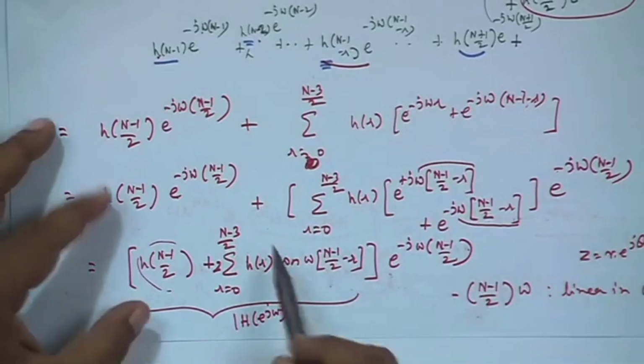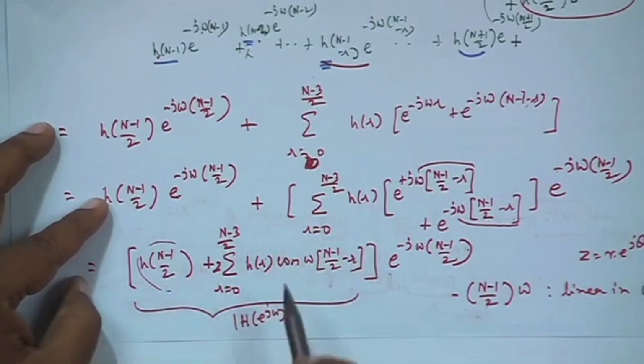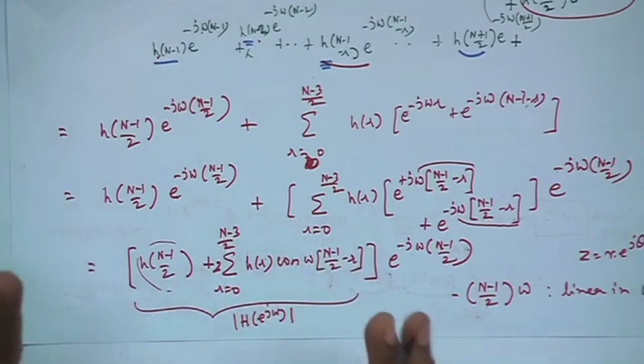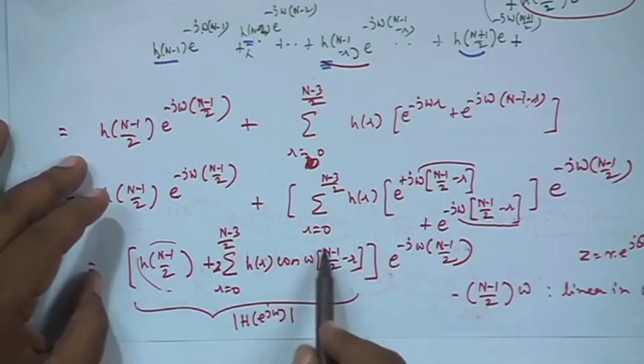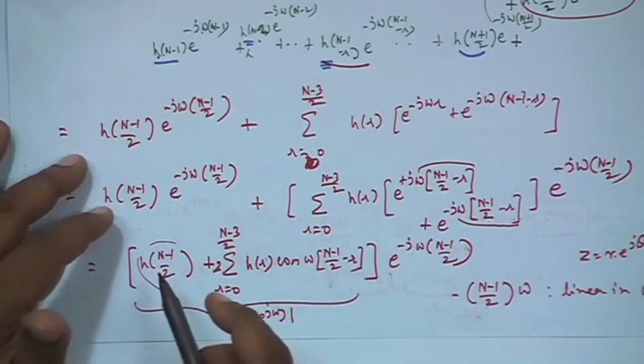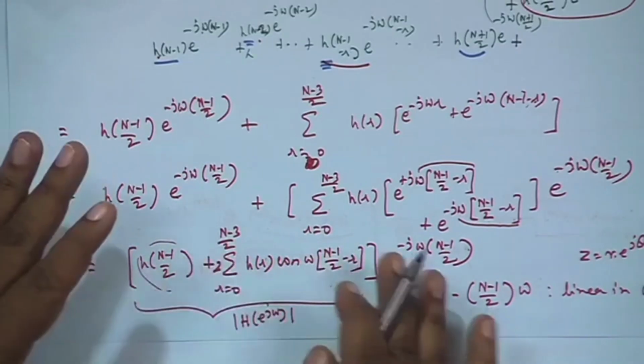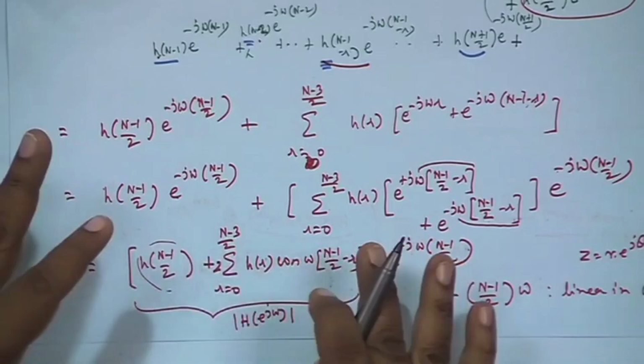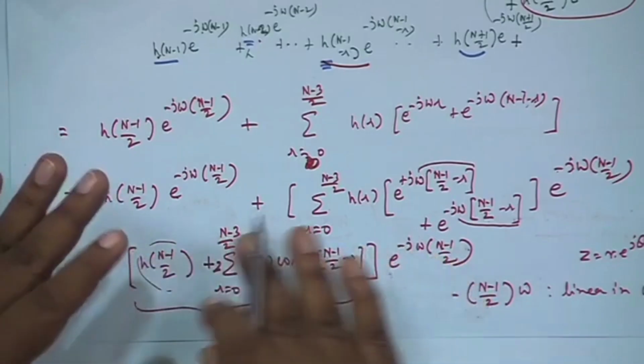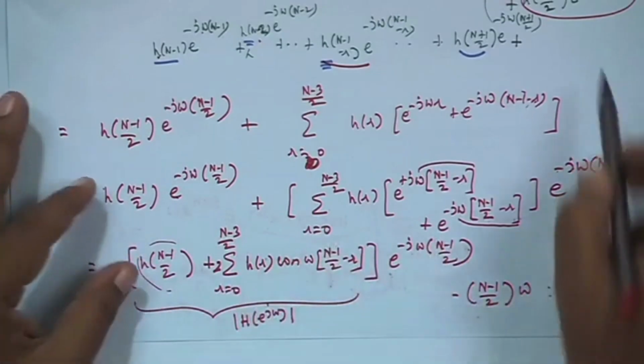So, that is why we try to design this filter coefficient such that within the pass band minus omega c to omega c, this does not change its sign, number 1, and its value, which is say positive now, is not changing its sign, it is not turning out to be negative. Its value also does not fluctuate much, it is kind of constant.